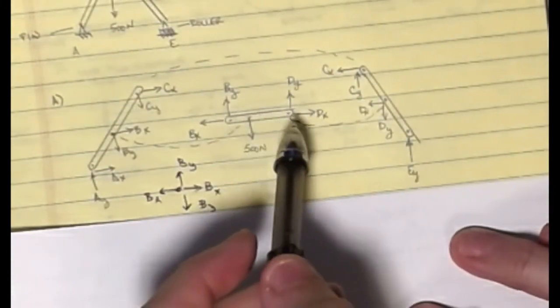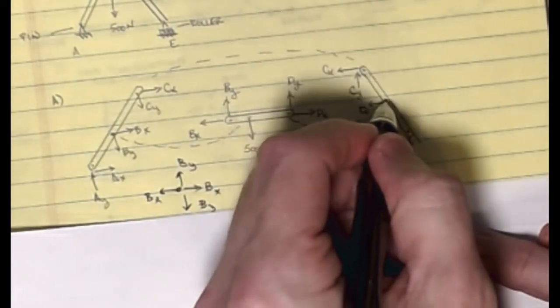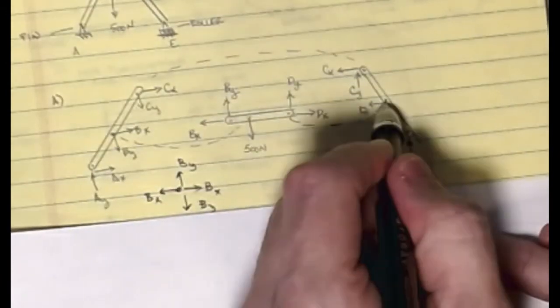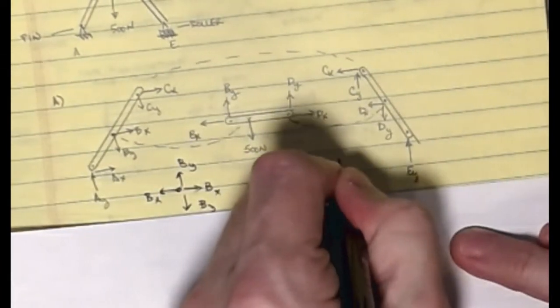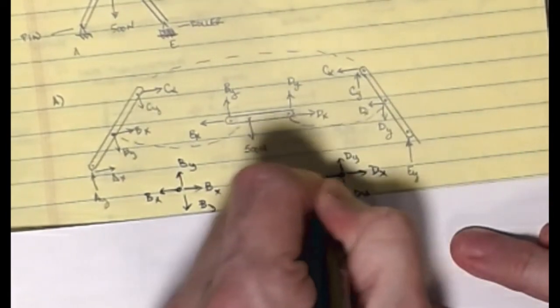All right, and then if I go over and I look at D, I can do the same thing with this, right? So if I do DX to the right positive, DY up positive on here, on the member that he connects to, even though it's not at the ends of the joints, I can still put that force at the hole that's in the middle of the bar. All right, and so DX is to the left and DY is down, but again, equal and opposite. So I go up, here's a DY, and then the other one was acting down, and then over to the right is DX, and then over to the left is DX. Those are the forces that are acting on the end of this bar as well as at the hole location on the diagonal. All right, and you can see again, it's in equilibrium, no major surprises for us there.